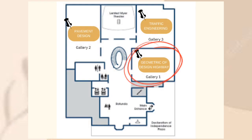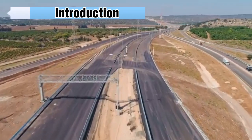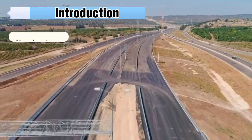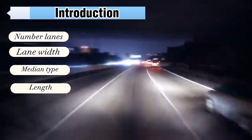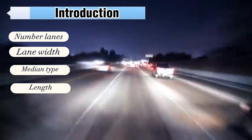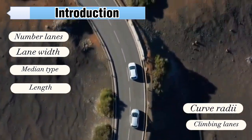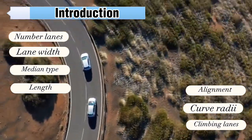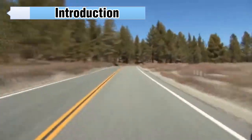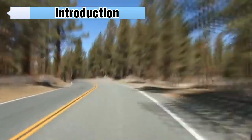Our first stop, the geometric design of highways. So the design of highways necessitates the determination of specific design elements which include the number of lanes, lane width, the median type and width, the length of acceleration and deceleration lanes for on and off ramps, need for truck climbing lanes for steep grades, curve radius required for vehicle turning, and the alignment required to provide adequate stopping and passing sight distance. Many of these design elements are influenced by the performance characteristics of vehicles.